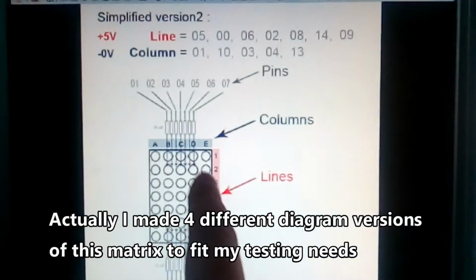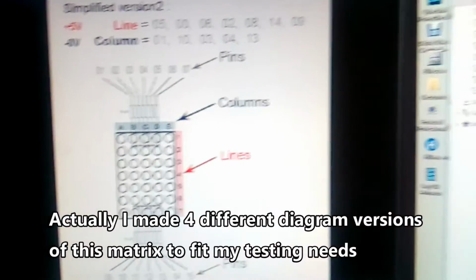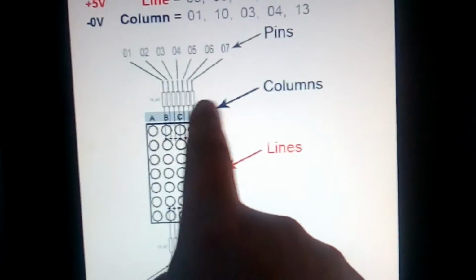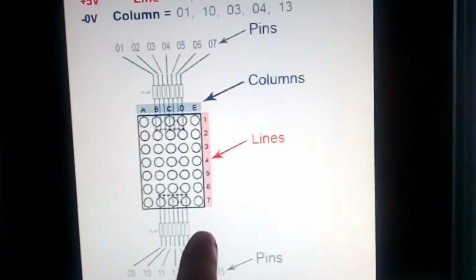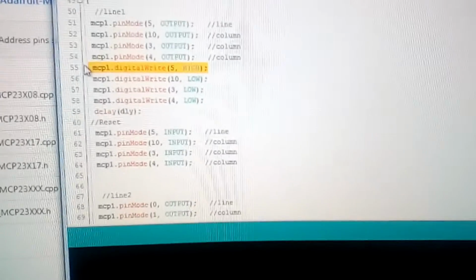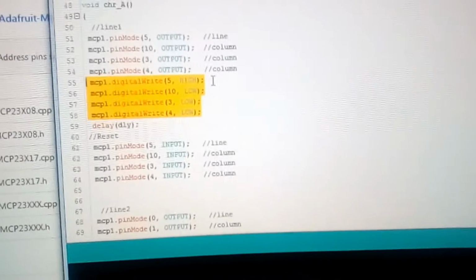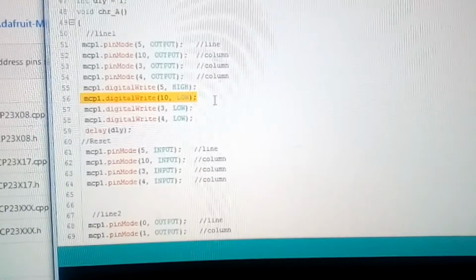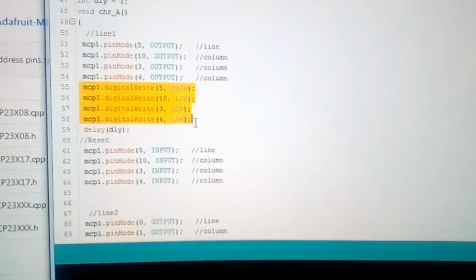By the way, this diagram, I made it after discovering how this module is working. I didn't have anything, and I had to invent one. Also, I imagine I have to put these resistors here, which I switched from 1 kilo to 300 ohms. Right now they are 300 ohms. And then I switched to high, and the corresponding plus and minus, positive and negative.